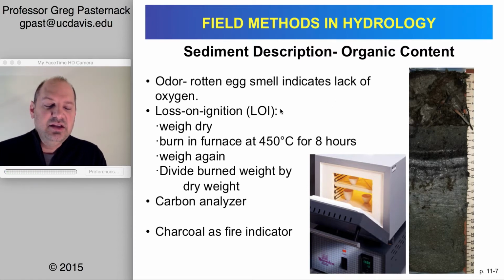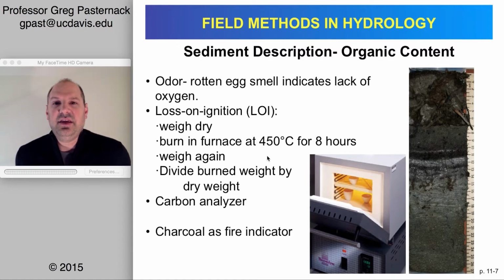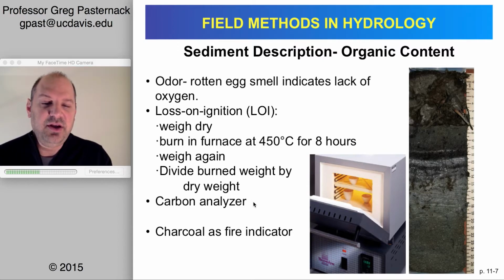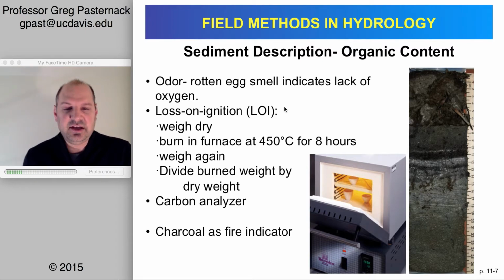And if we take a fraction of sediment, weigh it dry, and then burn it in something called a muffle furnace, where you can put it at like 450 degrees Celsius for 8 hours, weigh it again, then the difference between the dry weight and the burned weight is going to be the volatile organic content. A more sophisticated approach would be to use a carbon analyzer, but the basic thing that is very commonly used is just loss on ignition.